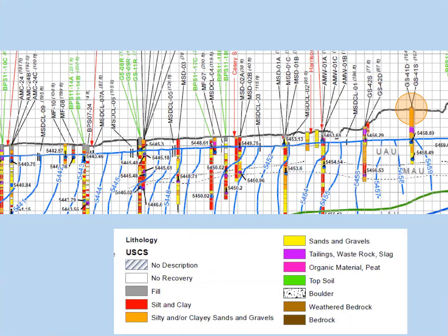And so they've just taken where they measured sand, or sand and silt, or sand and gravels, or silt and clay, and then they've turned that into very fine units in some cases, like right here. That's a bunch of different units. Here's where they tried to run the middle alluvial unit through here, and it's hard to agree that that's what it is.